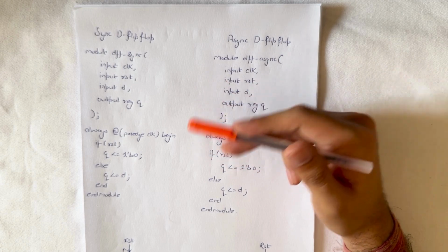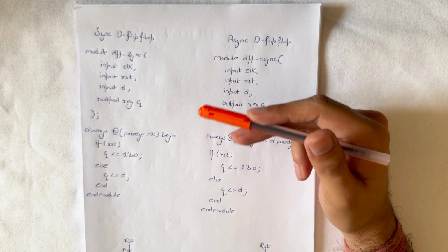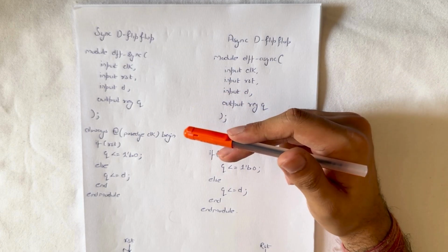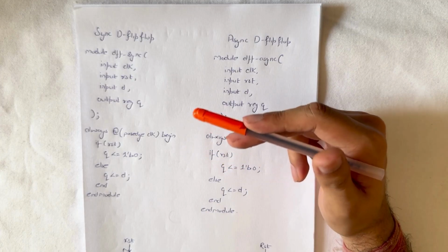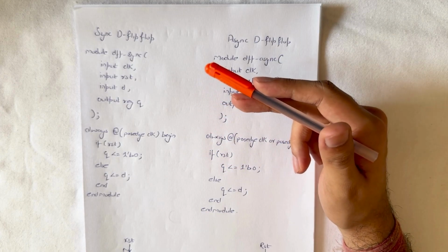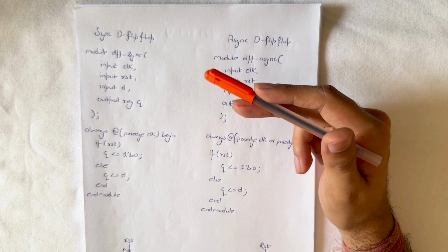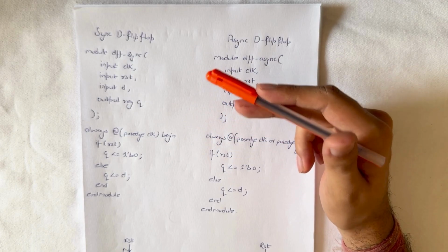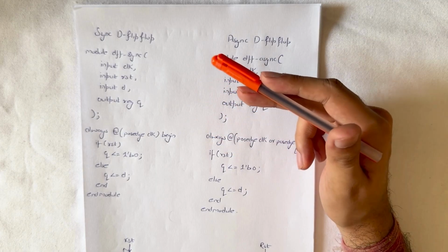For a simple design like this, the synthesis result will usually show one flip-flop cell being used. Sometimes the reset may add a small amount of combinational logic as well. Looking at the synthesis netlist helps us understand how our RTL description is translated into an actual hardware component.